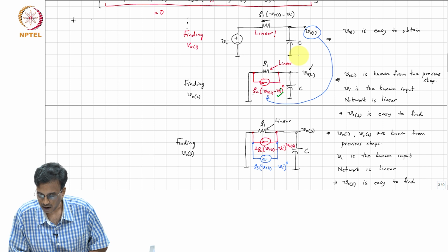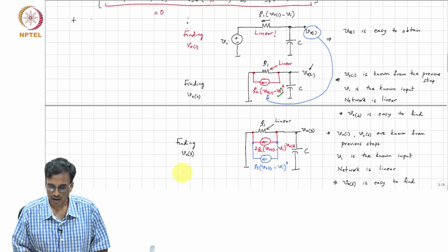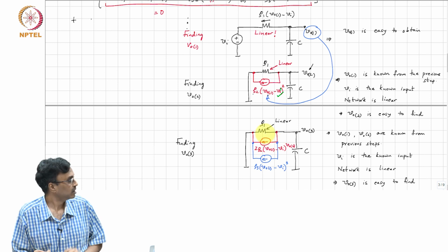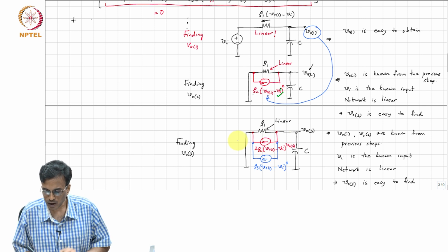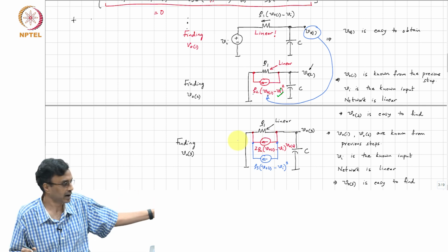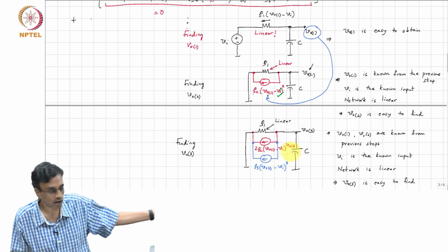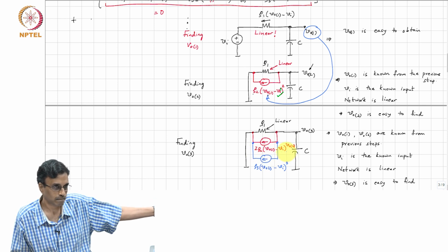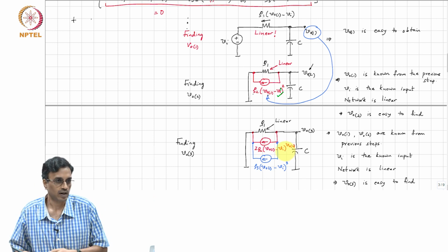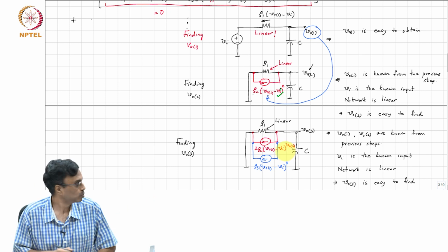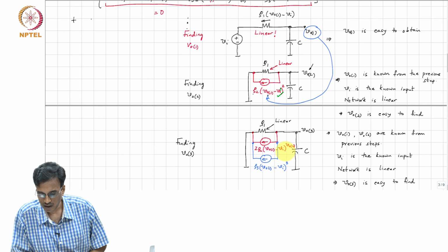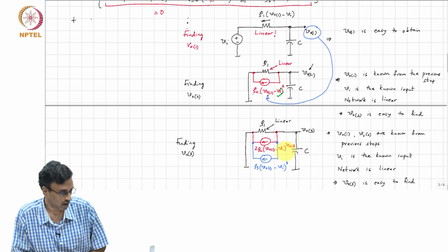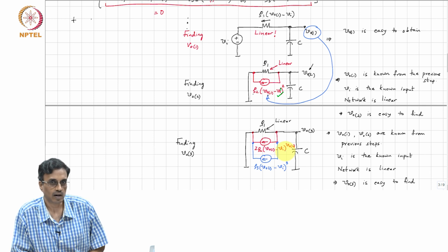To find the third order response, you again have the same linear network, but in parallel with the nonlinear element, you now inject a different set of currents. Basically you see all the third order currents that are being injected here, and so on. Most of the time, in a circuit that works properly, the second and third order distortion terms are often the most dominant, and therefore 2 iterations are good enough.